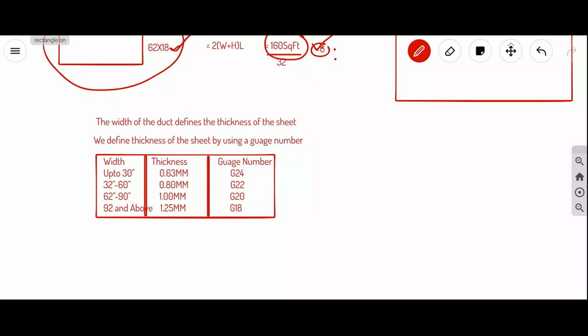Yes, that is the reason. Okay, that is also one logic we need to have. And for chilled water, the thickness of insulation is 40 mm, and the thickness for hot water insulation is 60 mm. The insulation material is PUF, polyurethane foam.